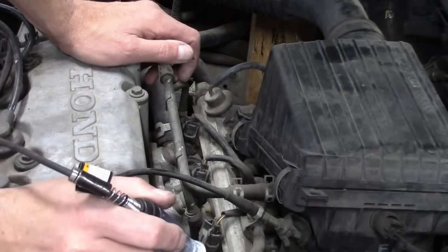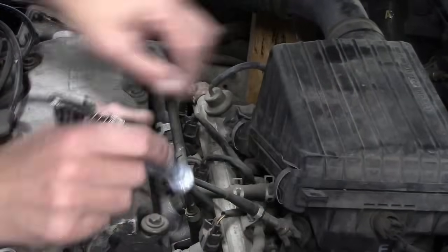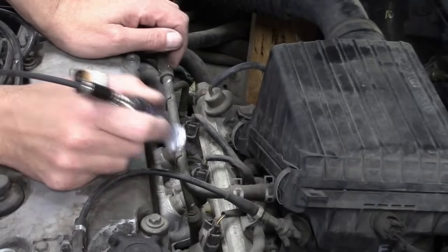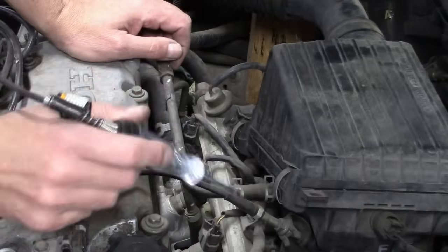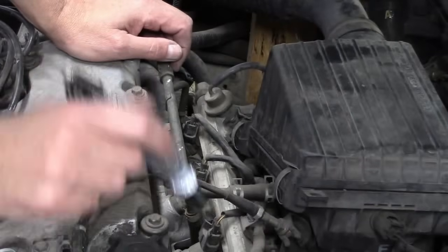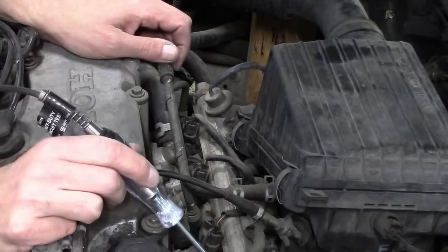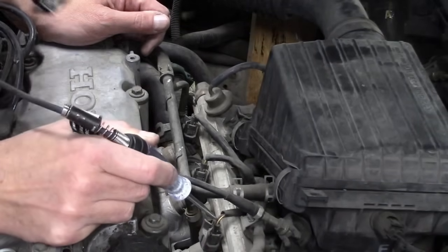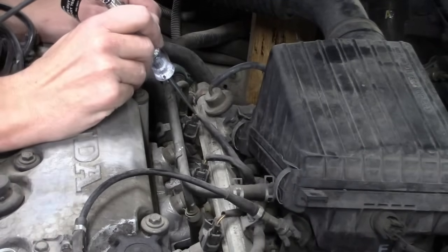Looking close at the wire, I can see we have a yellow with a black stripe wire here, a yellow with a black stripe wire here, a yellow with a black stripe wire here, and a yellow with a black stripe wire here. So what this is telling me is that on this design, we have a constant power feed that splits in 4 places, 4 branches to each injector. And then we have a different colored wire as the second wire. This one looks like red something. This one looks orange to me. This one's blue. And this one's a solid yellow.